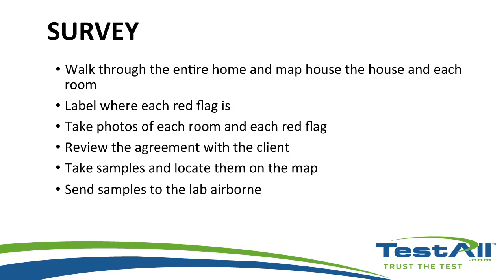Survey. If you're going to do a survey, you'll be walking through the entire building, home or office building or other indoor building. Map the building out with each room. You'll be looking for your red flags, mark them, label them, take pictures, usually 3: one entering the area, the other closer to your red flag, and then one of the red flag itself.